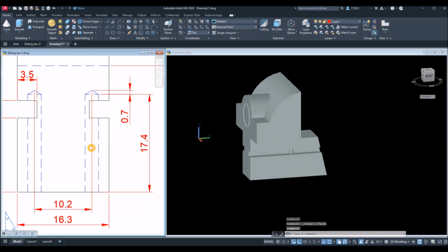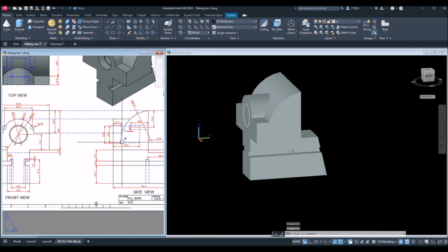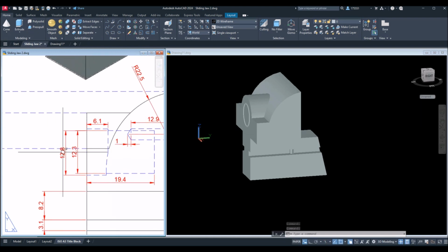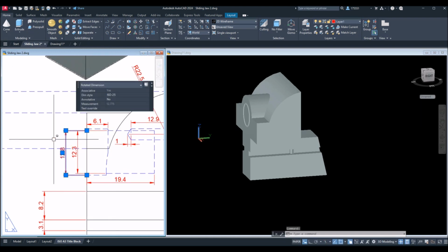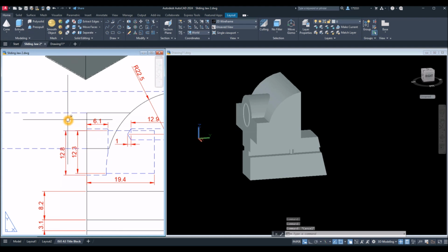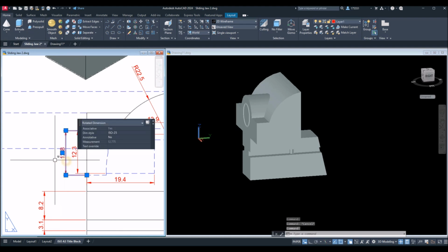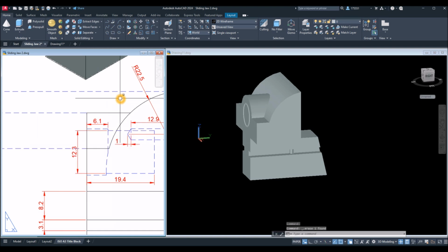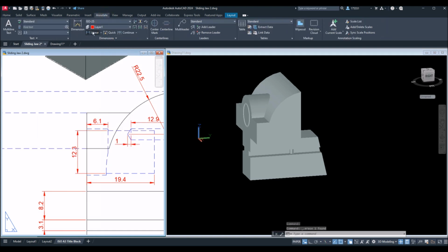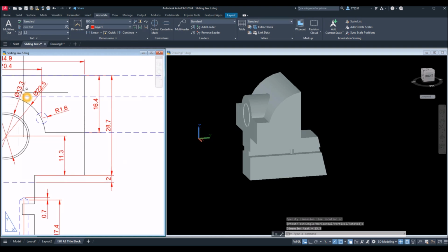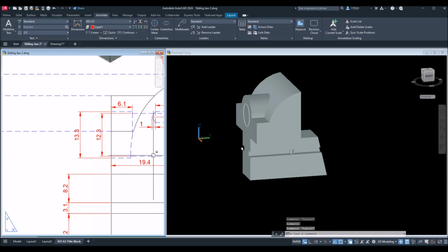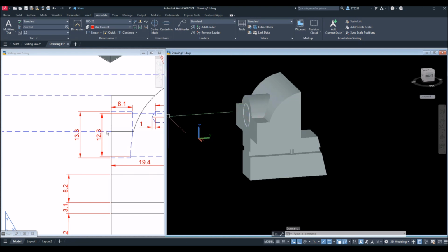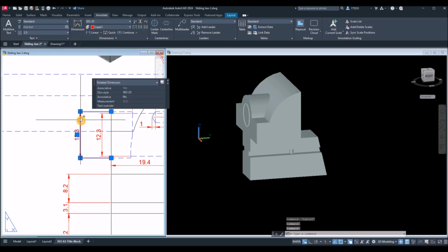And now I'm going to poke a hole through this object here, and looking from side view, the bigger one, the first circle, 2.8, no, I'm going to delete this one. I annotated, the annotation is wrong. So from this endpoint to this endpoint is 13.3, which is this circle here, 13.3. All right, so I'm going to extrude this one, the biggest circle. So this is the diameter.